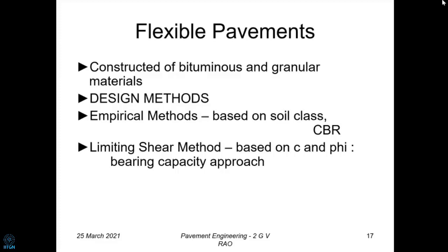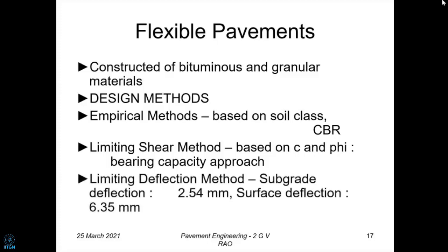That means we are trying to use the same kind of bearing capacity system of Terzaghi, wherein there's a cone formed between the foundation structure and the soil, and that is going down. So an extension of that is made by using the same C and phi, but somehow that is not acceptable to pavement engineers, so that got discontinued. And then, of course, the methods which are there is what we call the limiting deflection method. Limiting deflection method means the deflection of the surface is limited to something, and deflection of the subgrade is limited to something like that.